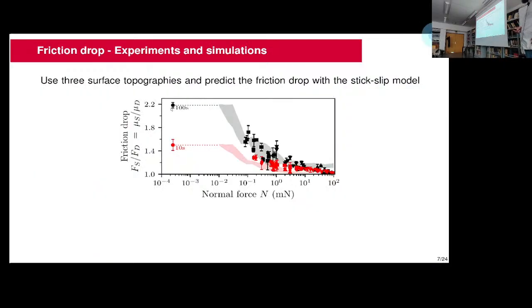Okay, so we are going from single to multi-contact asperity, and if we feed the results from the elastic contact computation into our small fiber bundle model, that's the shaded area in this plot, we actually find the same decrease of static friction with increasing normal force. And to compute the range of friction coefficient, we scan different sphere topographies to get rid of the specificities of each topography. So there are 3 different topographies shown here.